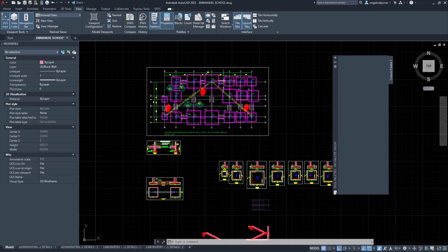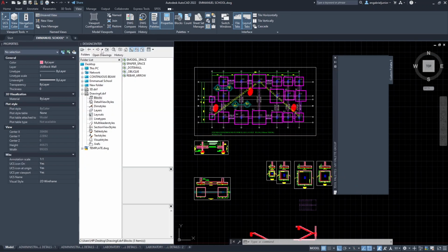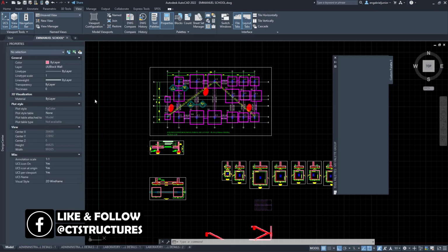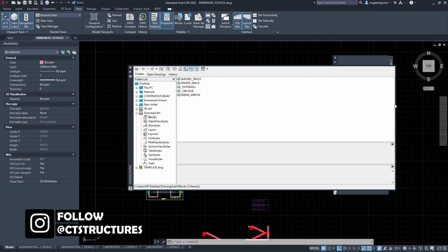Now, how do we add tools or objects into the palette? You can do that either in the drawing you're currently in, or you can also obtain objects from other drawings. For example, if you go to the Design Center, you can locate a drawing you've done before, then access the objects that are within it. I do not want to pin it. Yeah, I believe it does that.